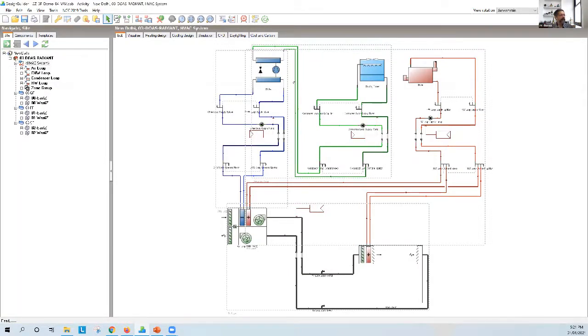If you think about it, the way the system is set up right now, you have one chiller, one cooling tower that cools the chiller. You have one boiler that provides heating. The boiler provides heating to a heating coil inside the air handling unit. It also provides heating to the reheat coil within each zone. Typically in India, you don't have any heating on the zone side on the VAV box, so sometimes it doesn't control the temperature very well in winter. But this is a very traditional VAV type design.